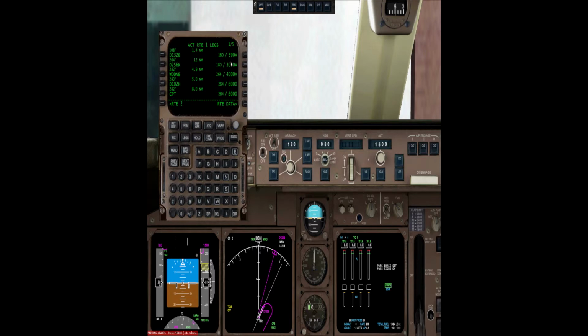And then we come down, make sure all the altitudes are correct here. You can see it's gone to 6,000, which is what we need on the SID. And then after that, it'll climb to 340, change to a Mach hold here. Go through, make sure there's no discontinuities. Right, it thinks we're going to land on runway 22 left at Kennedy, but we probably won't. Depends on the weather. Okay, so all that's done. So I think that's the FMC all set up.